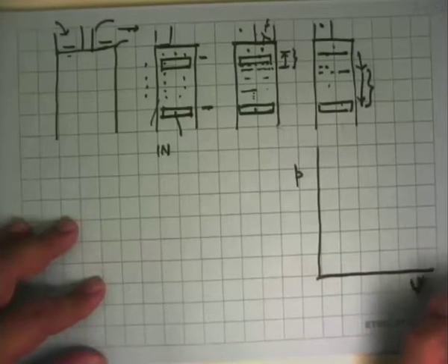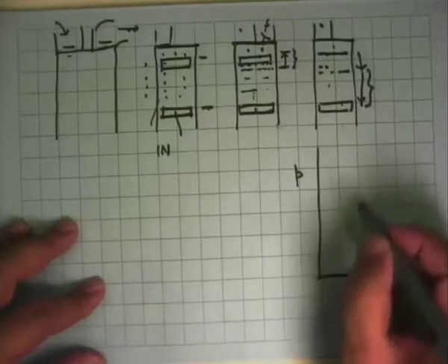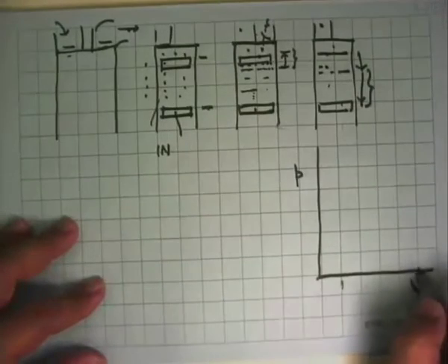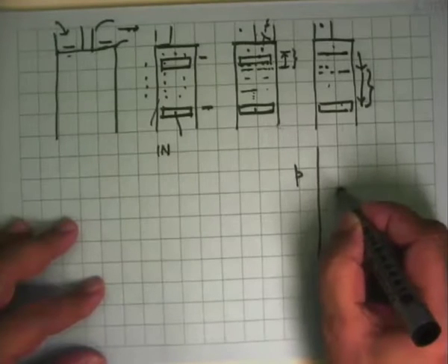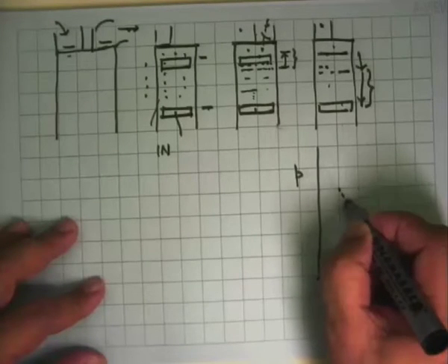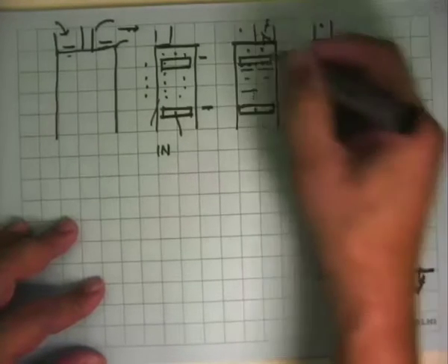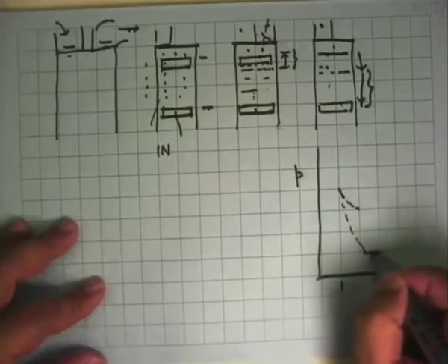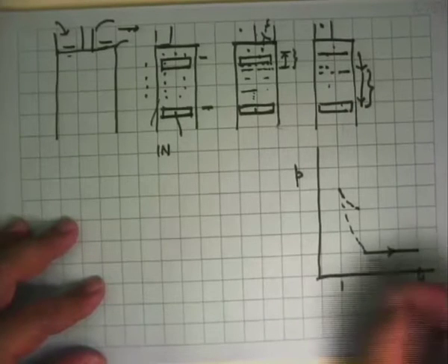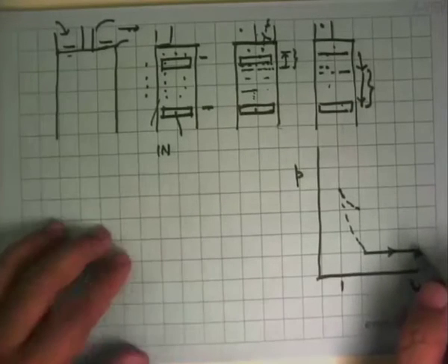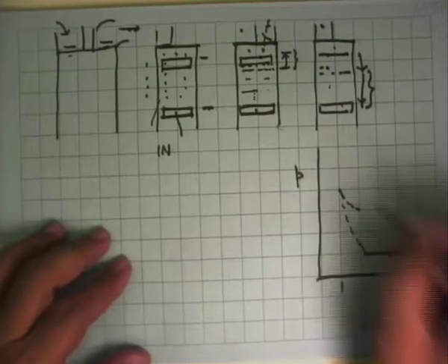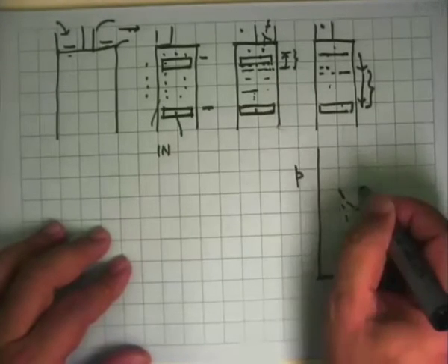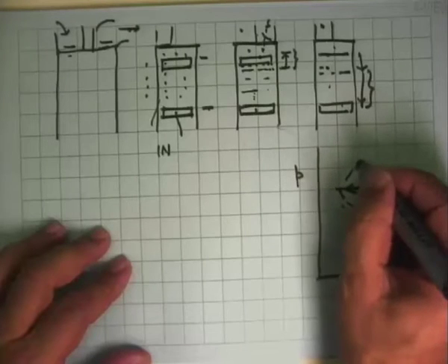Now you can put PV, also capital. So when the piston moves from top dead center to the bottom dead center, these are the two states. Here the pressure begins to decrease, and then it reaches a point and then it goes in. So this is when it takes in fresh gas. Then from here it begins to compress, it reaches the top pressure, and then from here this is the discharge,